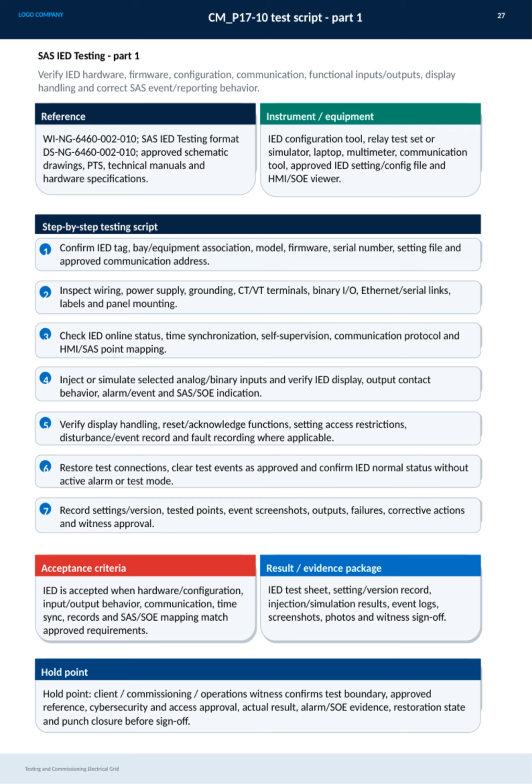Following that, we inject or simulate analog and binary inputs to verify the device's display responses, output contacts, alarms, and event indications. We confirm all these functions behave according to specifications. We also verify the handling of displays, acknowledge and reset functions, access restrictions to settings, and the recording of faults and disturbances, which are essential for reliable fault analysis. After testing, test connections are restored to normal, events are cleared as approved, and the device status is confirmed to be normal, with no active alarms or test modes left in place.